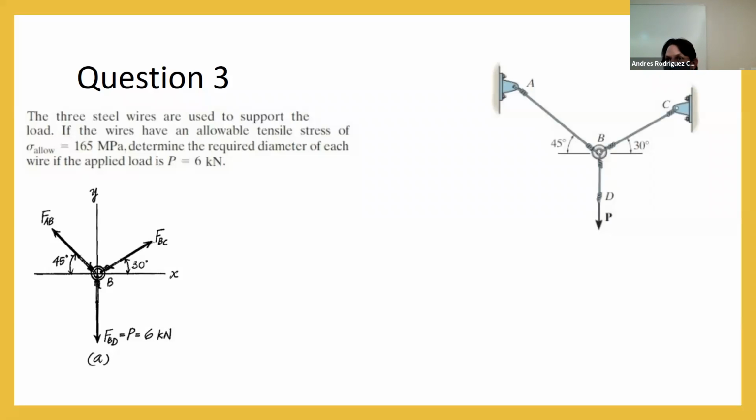Not sure 100%. Maybe I'm going to be the one that is going to handle the experiment in front of you, and you are going to be watching the experiment. Maybe one of you is going to be the one that is going to do the experiment, because the first one is going to be developed by me, but the second one is just to put a bar into pins, and we are going to apply torsion in the bar in order to obtain the shear force. So it's a small equipment like this one. So maybe one person is going to be able to manage the equipment, and we are going to use 3 bars. One is copper, the other one is aluminum, and the other one is steel.